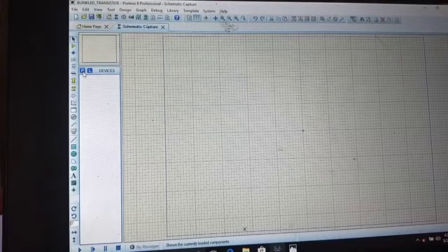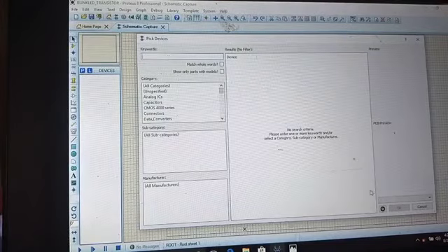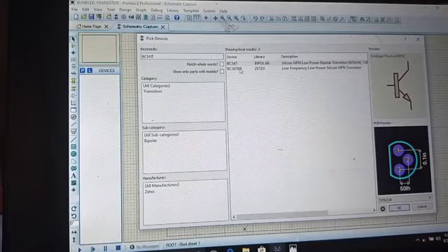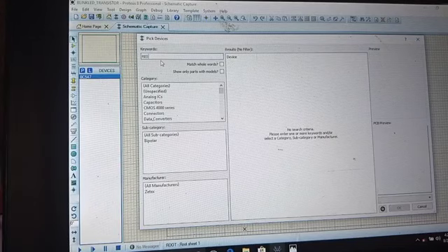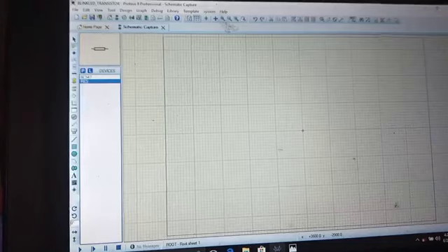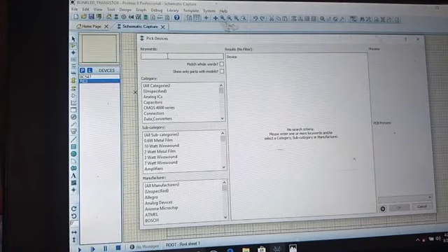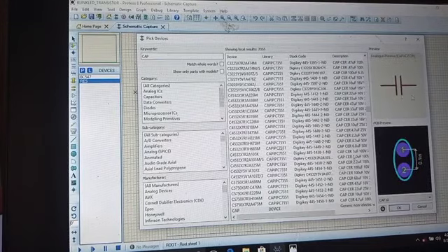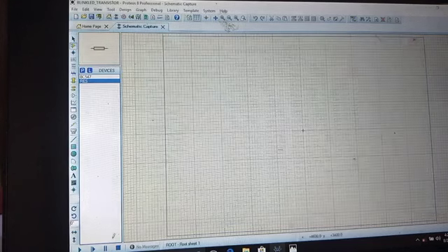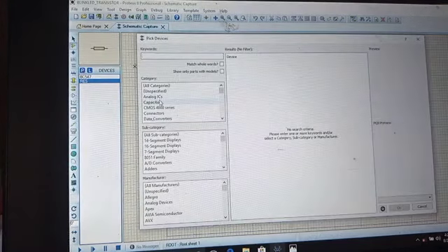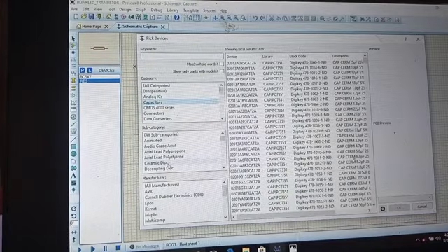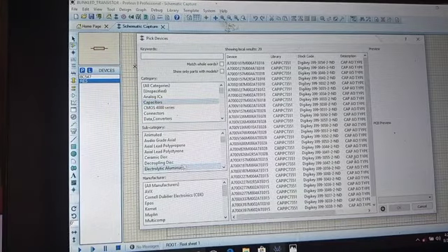The first thing is that P. That letter P is the same as the P on the keyboard, it is to select component. When you press it, you type the name of the component that you want to select. For instance, take BC547. I select there, I click there, it will appear under the P. The next is resistor. I can just press res. The resistor appears. Then I double click on it, or I click OK. It comes back. Then it will appear under the small menu that has a P and the L. So you see, this is how I pick my components one after the other.